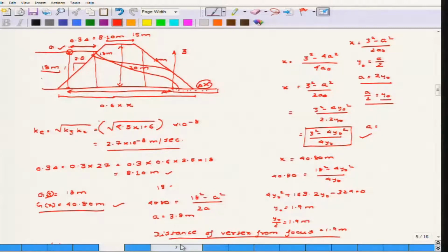So, you find out the total head multiplied with gamma W, and then you will find out the pressure at that point. Now, this sometimes helps in finding the effective stress at that point, because once you find out the total stress, then you subtract this pore water pressure from that number, and you will get the effective stress at that point. And in order to get the pore water pressure, you first have to know the phreatic line, because without graphical interpretation you cannot find out the pore water pressure at that point.